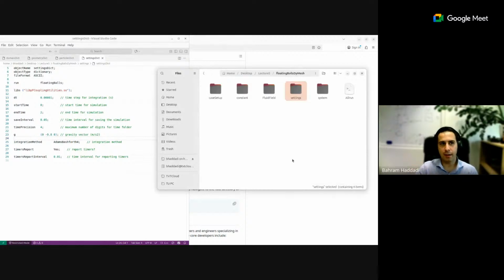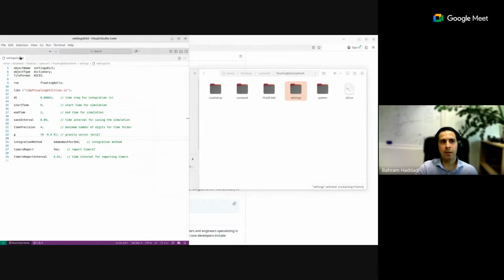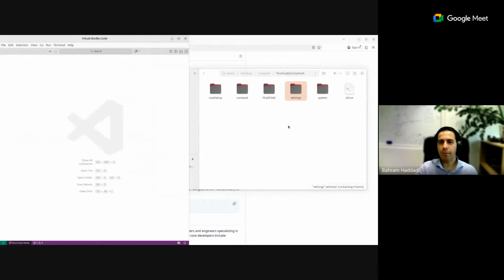Now let's go to the CFD side. For those of you who are familiar with OpenFOAM, you know we usually have three folders. One hosts the initial and boundary conditions, which is usually 0 or any other number. Then we have a constant folder, where constants like the viscosity models, the turbulence model, the mesh, and such stuff are stored. And then we have the system folder, which holds the numerical settings, and everything happens in there.